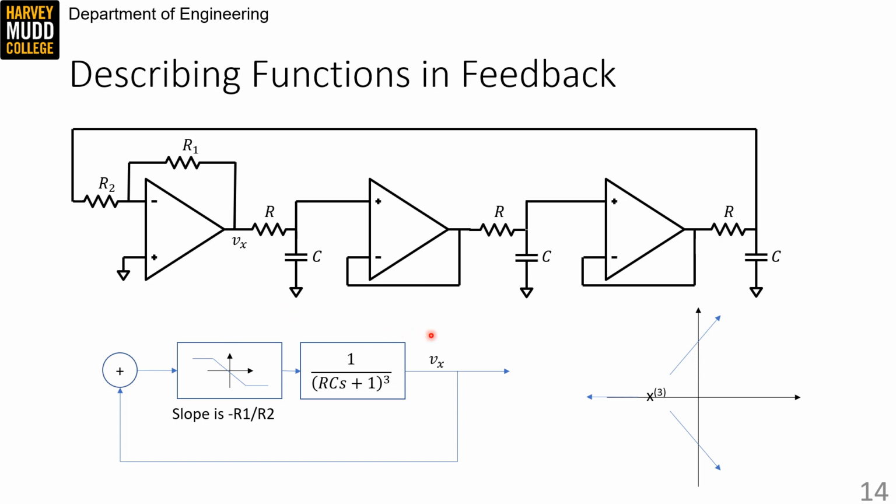So even without finding this exact describing function and just knowing its kind of qualitative behavior, we can learn things about our startup behavior. We start with right half plane poles and they settle onto the j omega axis. Our resistance to perturbations: the describing function will force the poles back to the j omega axis. And our safe range of gains, which is that we can probably go bigger than 8, but probably not smaller. We can also guess that we'll get more harmonics if we increase our gain, because it shortens the linear range of this nonlinearity, which is a neat fact too.